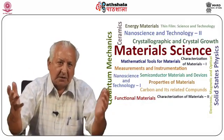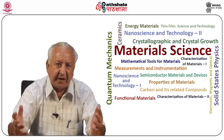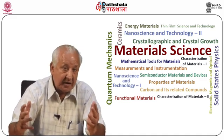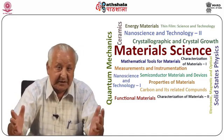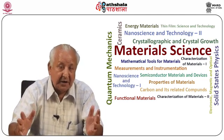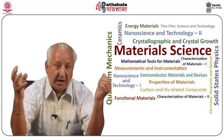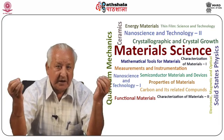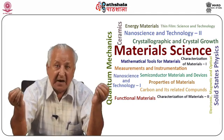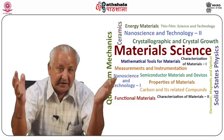Bridgman-Stockbarger growth. The techniques were originated by Bridgman in 1925 and Stockbarger in 1938, and so are named after them. In these techniques, a crucible containing the material to be grown is lowered through a furnace in such a way that the lowest point in the crucible and the solidification surface rises slowly up the crucible. It means that the melt contained in the crucible is progressively frozen to yield a single crystal.